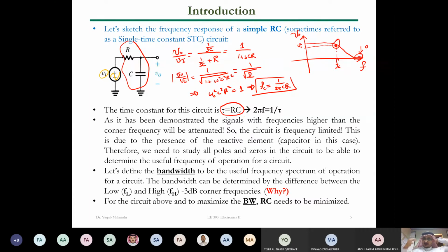And we also have an interpretation for this in the frequency domain. This is the corner frequency of the system. The inverse of the time constant, which is 1 over tau, is the corner frequency of the system. So this is nothing but 1 over tau, okay? And we have a lot of analysis, and we can relate these two things together. But in general, if you are interested in finding the corner frequency of the system and you have a simple capacitor and resistor, just find its time constant and then take 1 over the time constant.